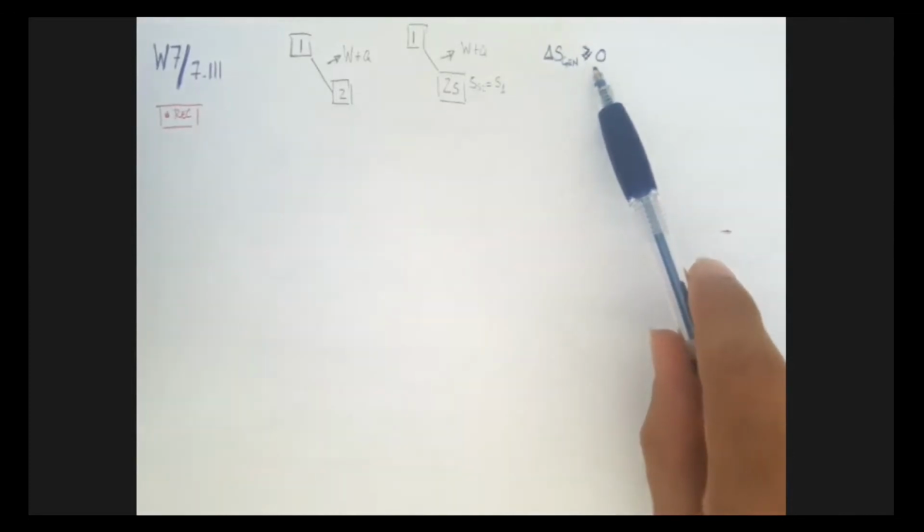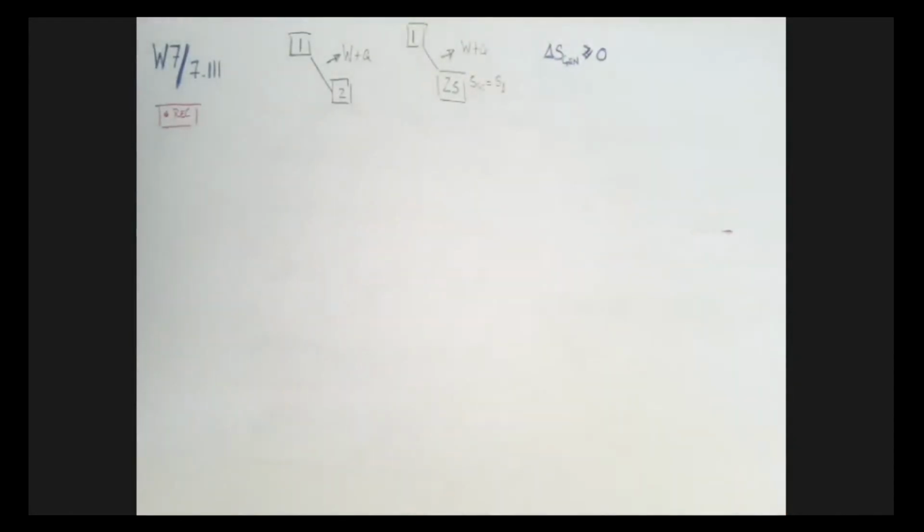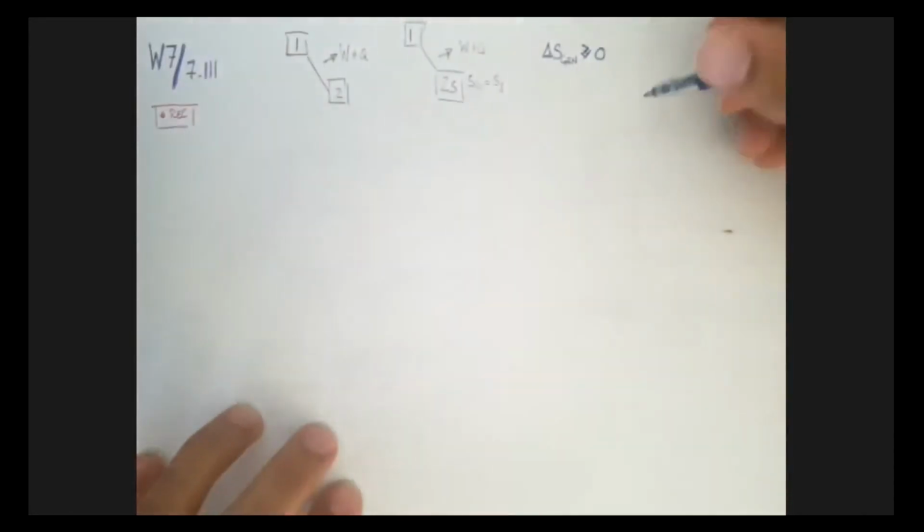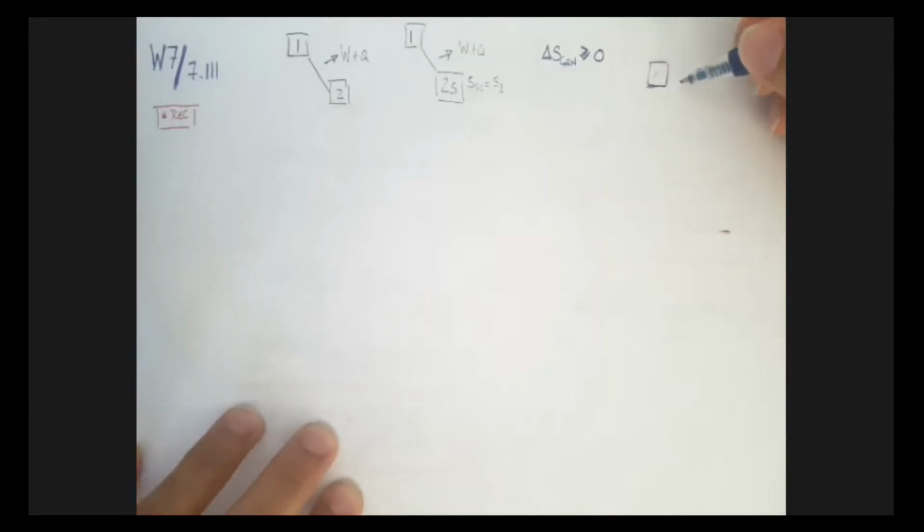Another way to think of this is to look at a given system. Anything that happens inside it should have an increase in entropy. If I have a negative entropy change from state 1 to state 2, it means I have to have either a positive entropy in the surroundings that compensates for that, or an even greater one, so that overall I have a generation of entropy.